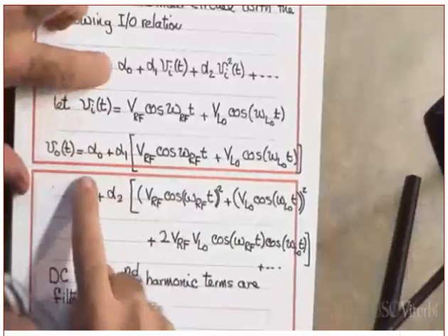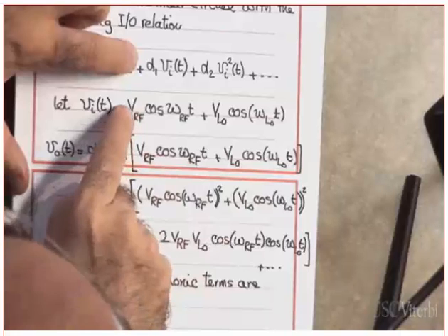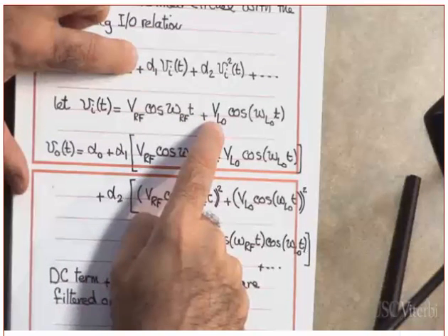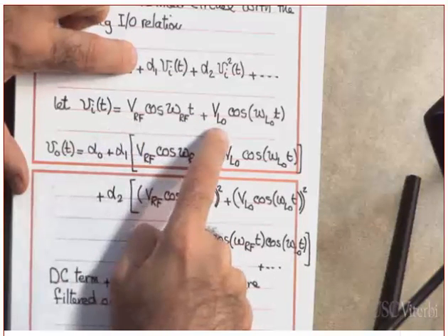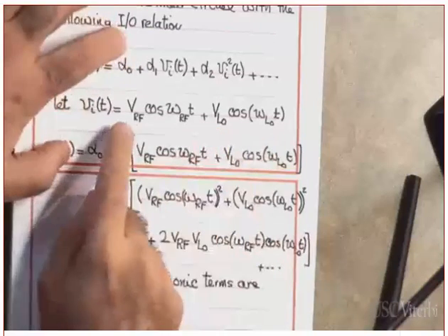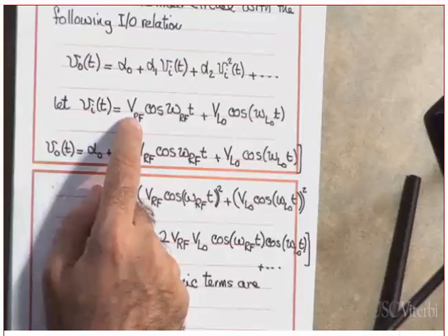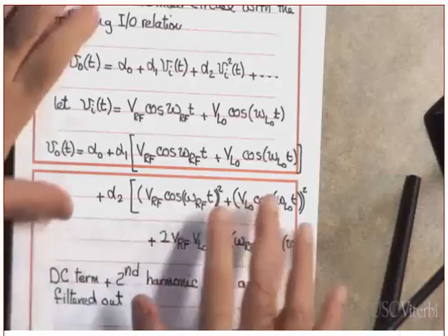So what is V0(t)? Alpha 0, which is this. Alpha 1, this sum. Notice, by the way, I did not assume that this is equal to this, because that assumption does not make any sense. Do you agree? Why does it not make any sense? This is weak, this is strong. Did you get this or not? Now, but keep in mind always, this VRF actually went through the LNA. Did you understand that or not? So it's not exactly the received voltage, but it's the received voltage after it went through some amplification stage, the LNA. Yes or no? Okay, good.